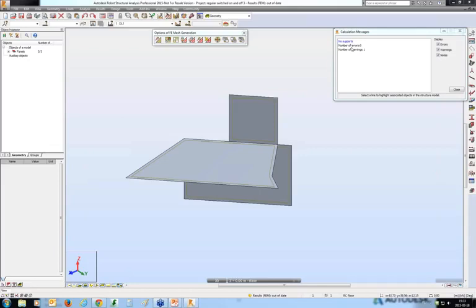Sometimes I verify the model and get no mesh problems, and then I try to run calculations, which then brings up incoherencies. And the response was, after playing with meshing or in between, you can run correction to merge generated nodes on edges, or run model generation before running verification. If I may add something, that may happen when you use local mesh generation.